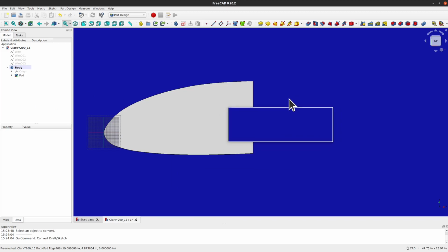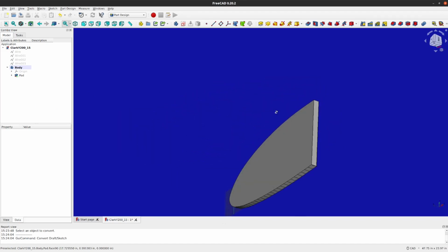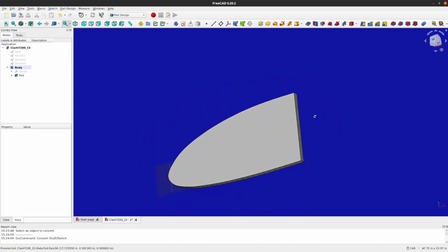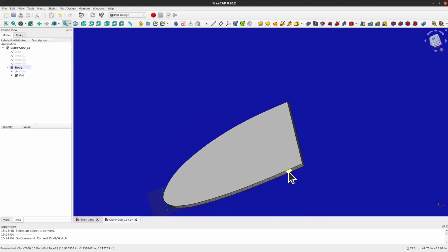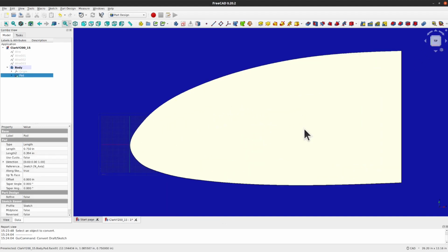So let's take a look at it. Oh, we can rotate it around, take a look at it. So you can see it's got some thickness to it now. And you can see all those little edges of our 200 points have now made little panels along here. But that's okay. Let's go ahead and go back to our top view. Now this is good enough to make at least a flange form block. I probably want to have lightning holes in here that we'd add, but for now I'm not going to worry about that. What we want to do next is put this into a technical drawing.